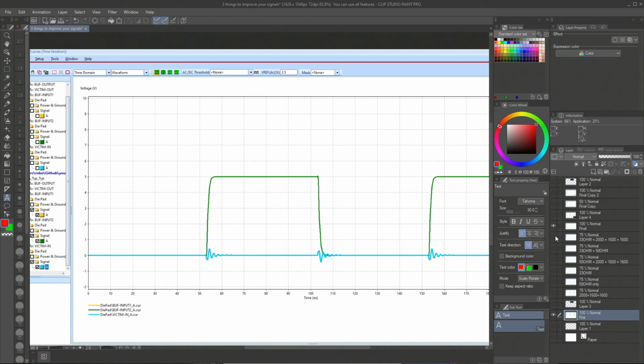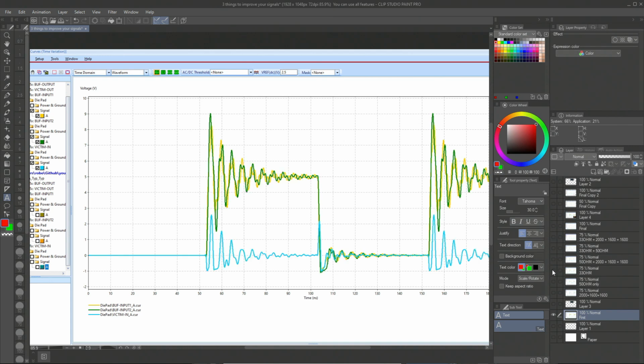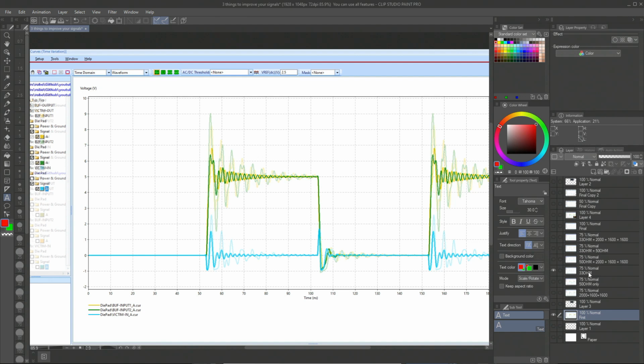There are two very interesting things. Watch this. If we enable only the 33 ohm series termination resistor, this is what we will get. And if we compare it with this situation, when we enabled the 33 ohm resistor and also did the length matching of the branches, this is what has changed. See? So basically, the length matching of the branches removed all this ringing which is here.